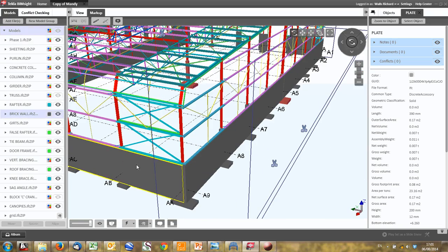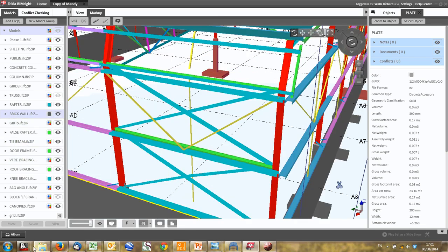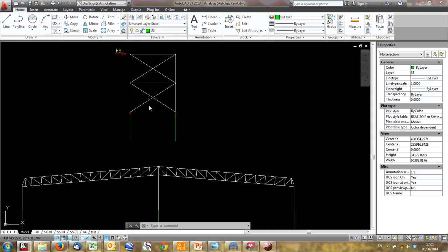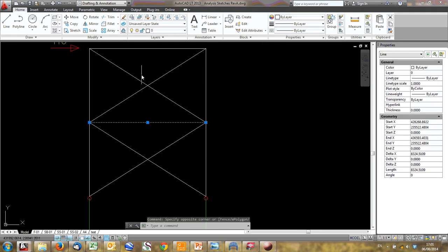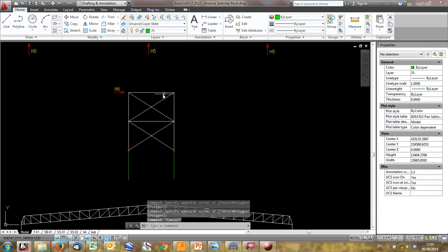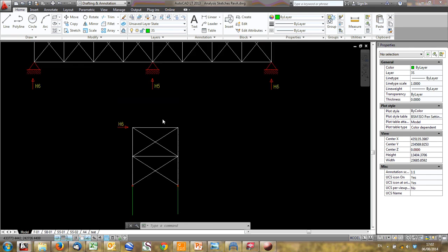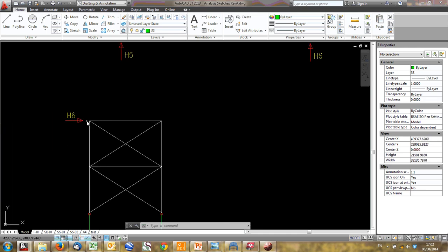So I've modeled this top part, and that'll carry the loads all the way down. In this bracing, as I said before, it's tension only, but just be careful: these diagonals are in tension, these horizontal members need to be designed for compression. So what we normally do is make them circular hollow sections, which is a pipe basically. You have a pipe here, a circular hollow section, and this thing can carry the load. So the load will come down in compression, tension, compression, tension.